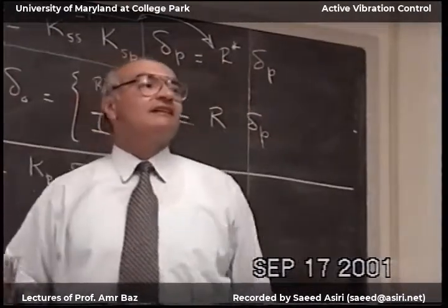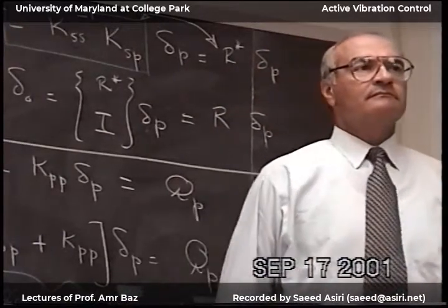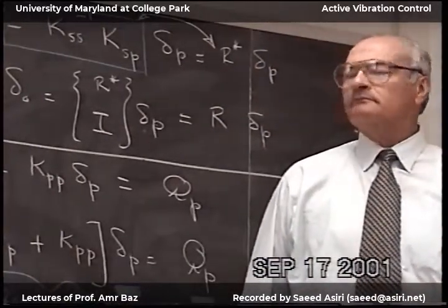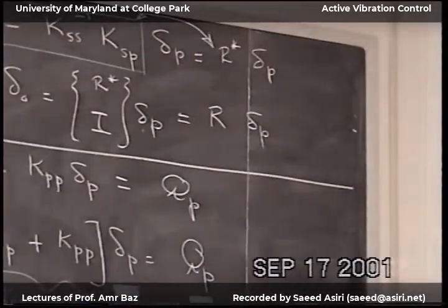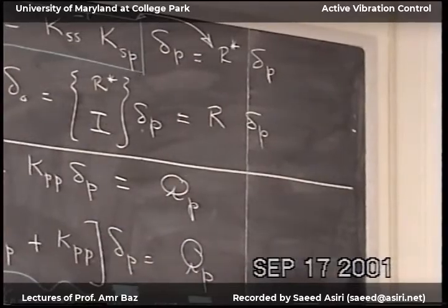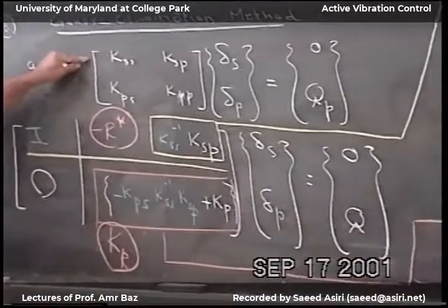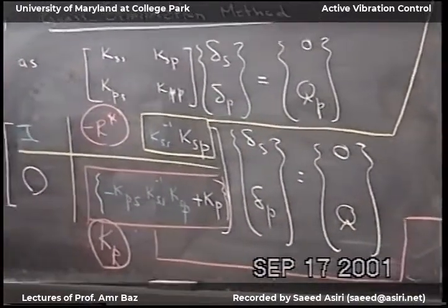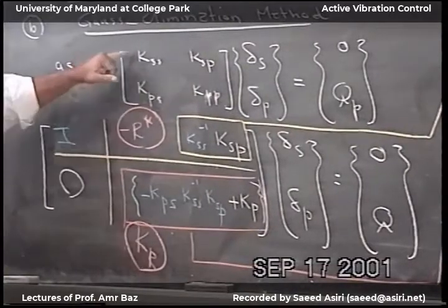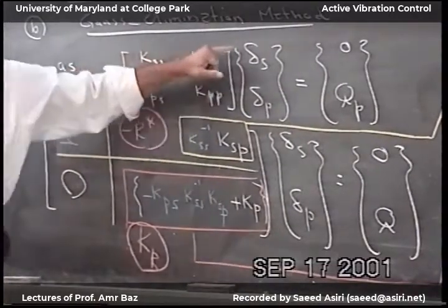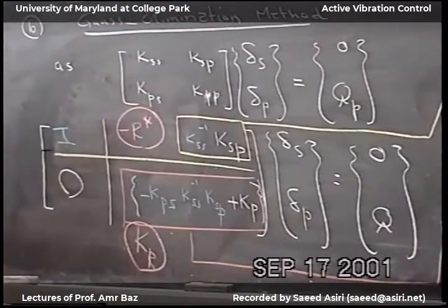Any questions? We're still involving an inverse of KSS, which is normally a huge matrix, large matrix. No. This is not done by, this is not inversion. This is done row by row reduction. So you take a pivot element, you divide by the pivot element. One row at a time. It's not block matrices. We'll show you in the example. I'm not gonna invert matrix. Take one row and do the Gauss elimination. Okay?